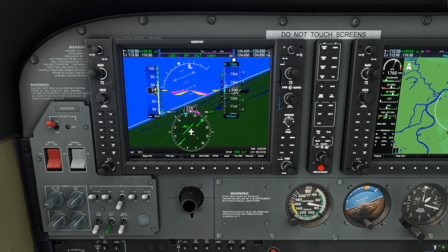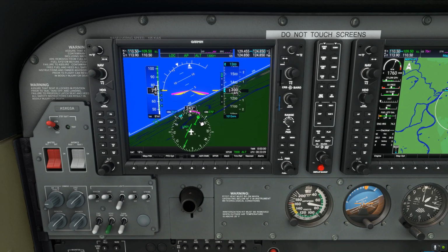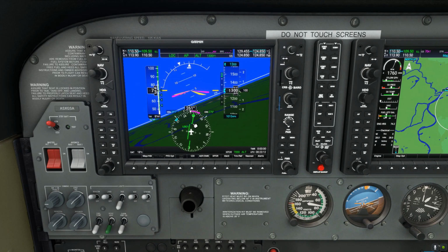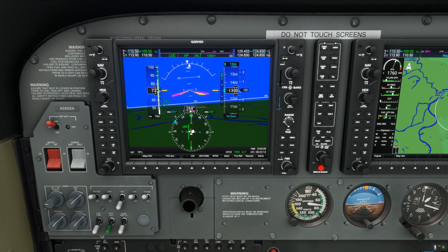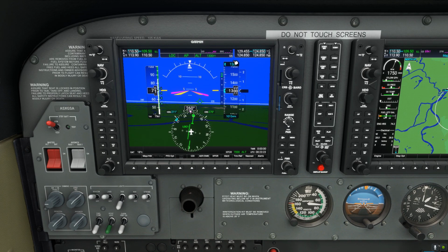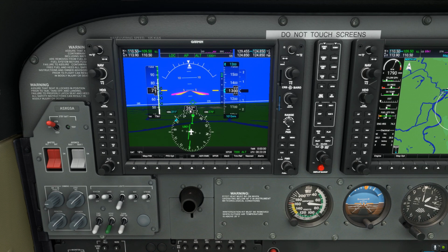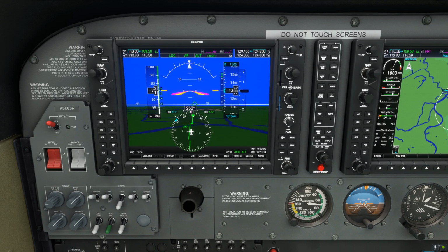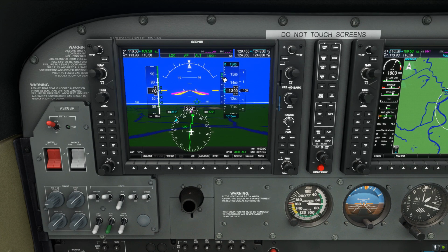Glide slope is going to stay in white because the glide slope indicator has not come down, but the autopilot will line us up. Line these lines up, essentially. So you could press your approach mode this early, and it will follow even the glide slope when this starts to move down. Just watch my speed there, I didn't realise I was going so slowly, but we don't want to speed up too much, because we will start descending on the glide slope any second. So as you can see, by pressing that approach mode button, localizer will lock in green, so it's locked onto the localizer. Before you know it, it will lock onto the glide slope, because this will start moving down.